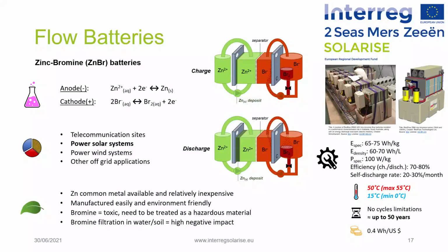During discharge, the reverse process occurs. The zinc metal plated on the negative electrodes dissolves in the electrolyte and is available to be plated again in the next charge cycle. It can be left fully discharged indefinitely without damage. The main characteristics of a zinc-bromine batteries are the following. High specific energy compared to lead-acid batteries, 100% depth of discharge capacity on a daily basis, no shelf life limitation, as zinc bromide batteries are not perishable, unlike lead-acid and lithium-ion batteries, for example, scalable capabilities.